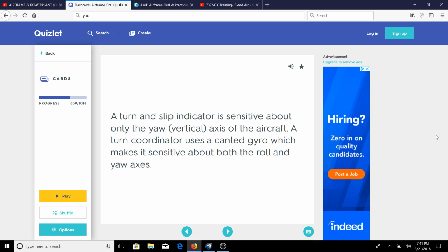What kind of system is used to measure the exhaust gas temperature of a turbine engine? An averaging system made up of a series of thermocouples arranged around the inside of the exhaust duct of the engine. What would likely cause the needle of an electrical oil temperature gauge to peg on the high side of